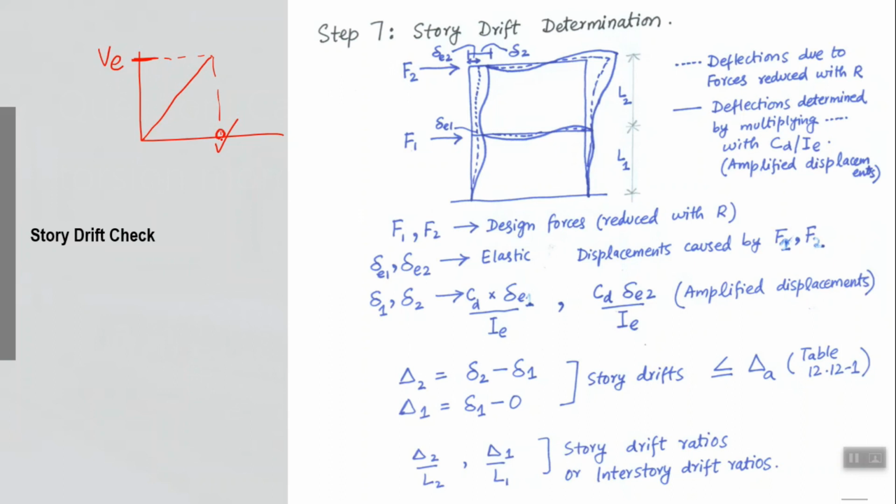So this deformation is the actual deformation which the future earthquake is going to produce in your structure. But what we do, instead of applying VE, we apply VE over R, right. We apply VE over R, which means that the analysis will give us a displacement which is this one, right, and not the actual.